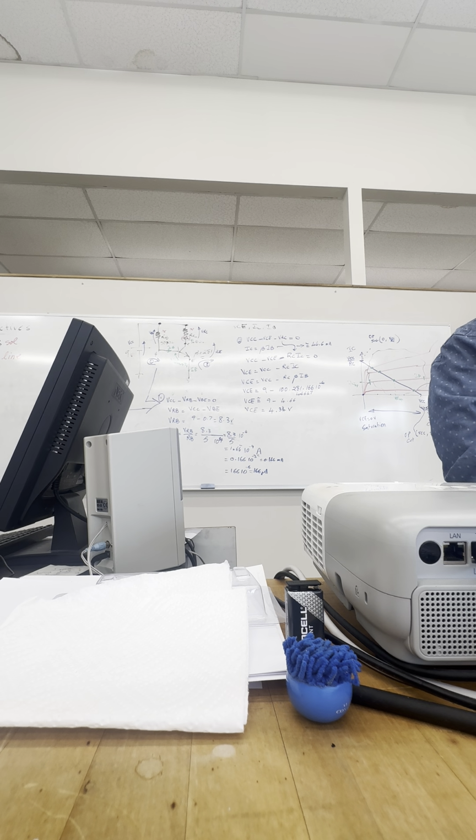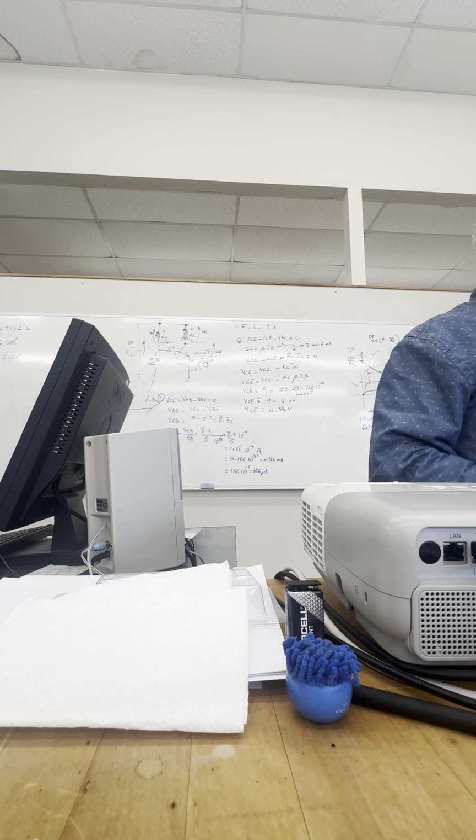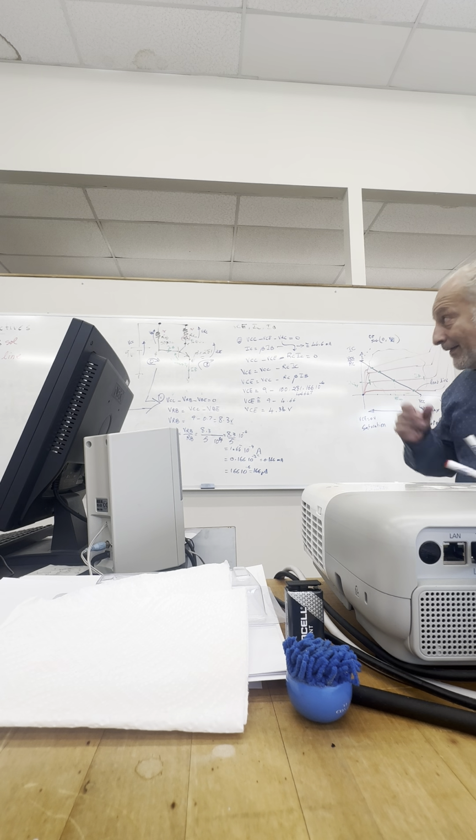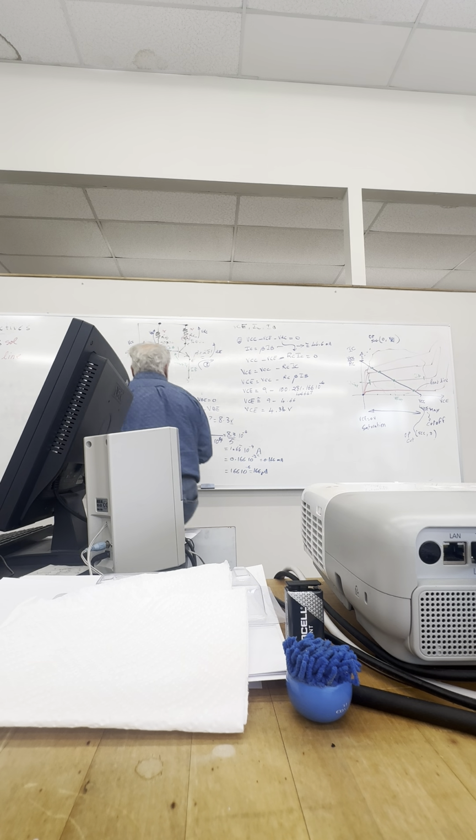Where you want the load, the max current, that's at the collector of the transistor. Don't touch that area. Typically, if it's a power transistor, you'll see them. They're beefy, they have fans and so on. I mean by that, metal stuck to it, to dissipate heat. You'll be amazed what's out there. It's not the little tiny doohickey you have in your bag, if you're controlling motors, that is.